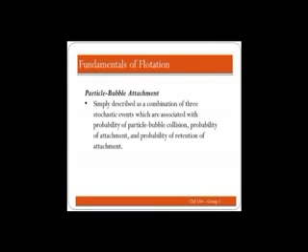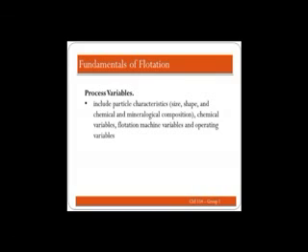Particle bubble attachment is simply described as a combination of three stochastic events which are associated with the probability of particle bubble collision, probability of attachment, and probability of retention of attachment. Process variables include chemical variables, flotation machine variables, operating variables, and particle characteristics such as size, shape, and chemical and mineralogical composition.